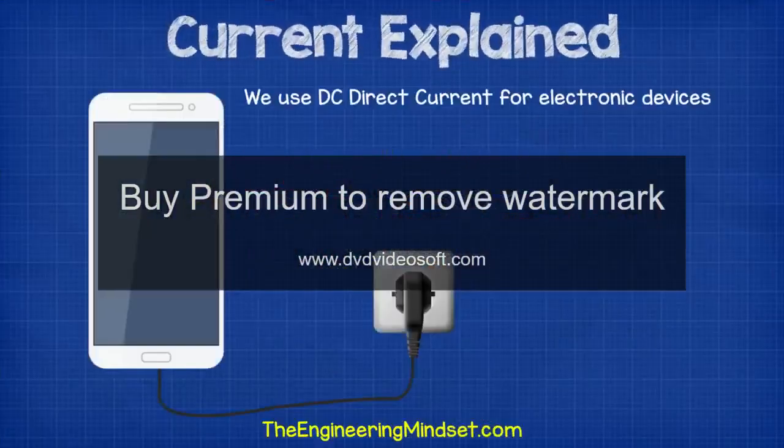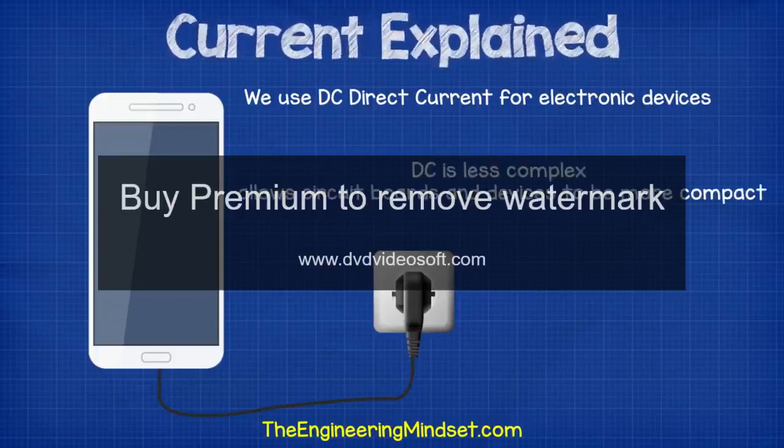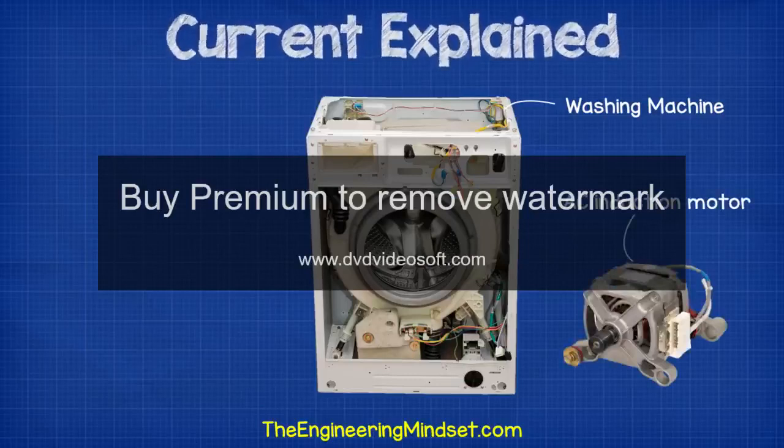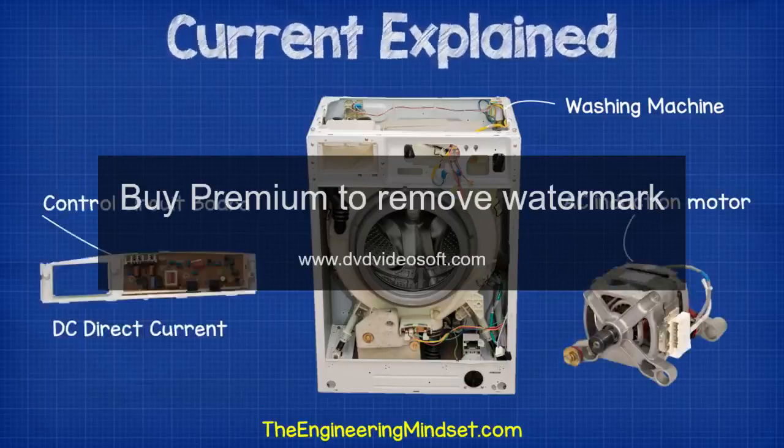We mostly use DC direct current in the circuit boards of small electronic devices like laptops, mobile phones and televisions. That's because DC is easier to control and allows circuits to be smaller and more compact. Many appliances will use a combination of AC and DC. For example, a washing machine will use AC for the induction motor, which is used to spin the tub with the clothes in. But the circuit board, which controls the settings, the lights, the timers, as well as how fast the motor spins, will use DC power.